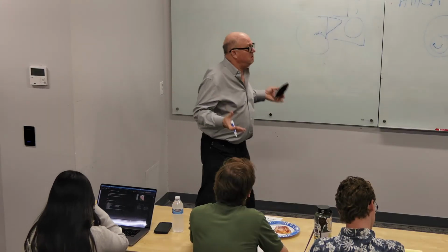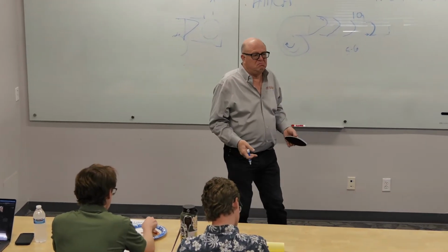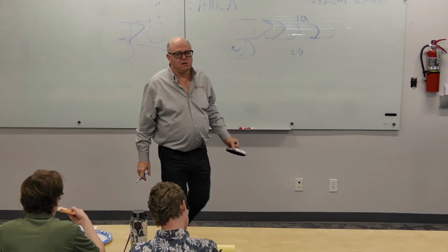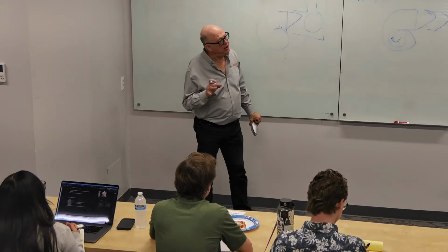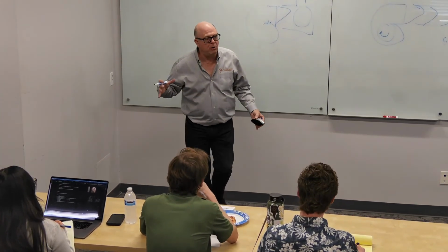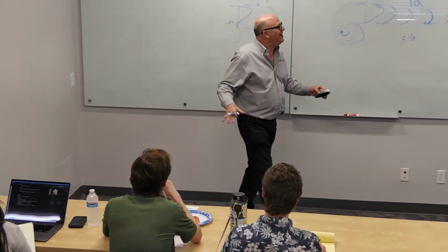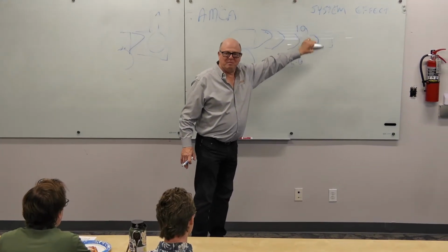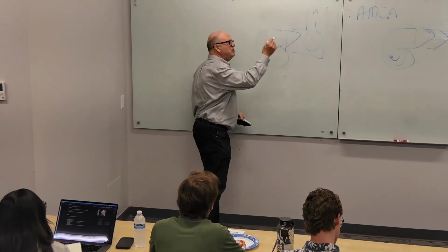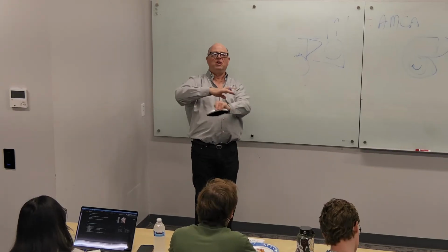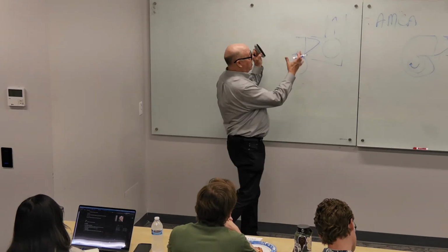If you picked just the average forward curve fan and you picked it to move 5,000 CFM at 2.5 inches, this correction is going to be probably more than an inch. Now think about what that does to how much more horsepower you need, how much faster you got to spin it. It utterly invalidates the fan curve that was measured out here based on 10 duct diameters. You don't do this. This is a mistake. Never, never do this.